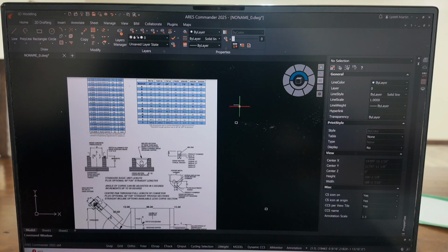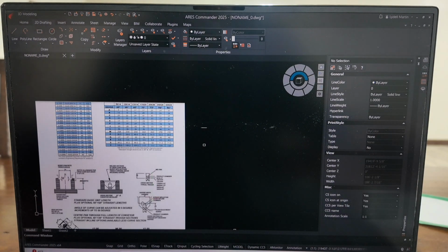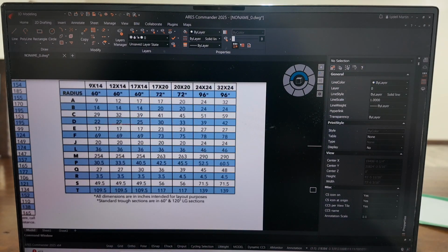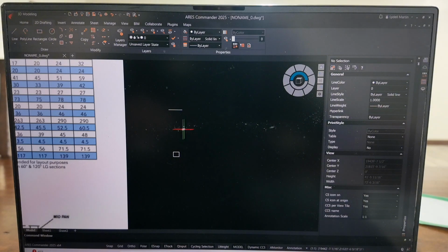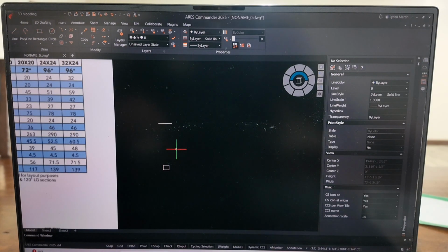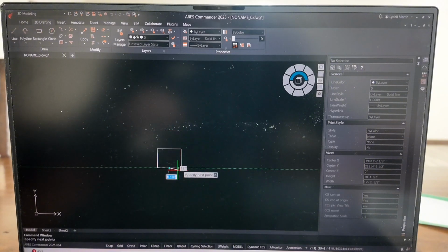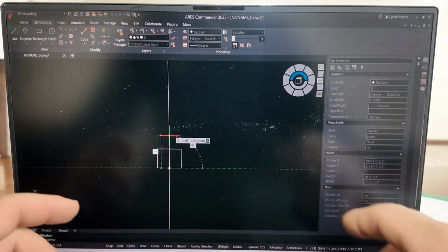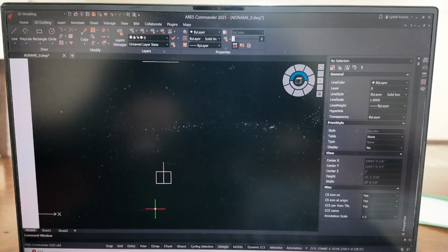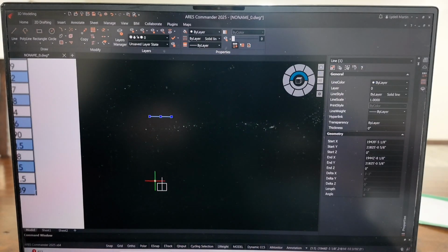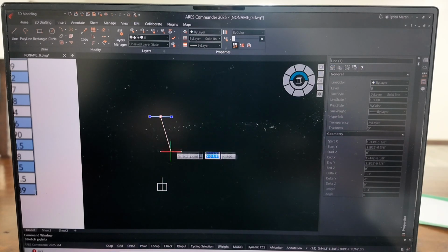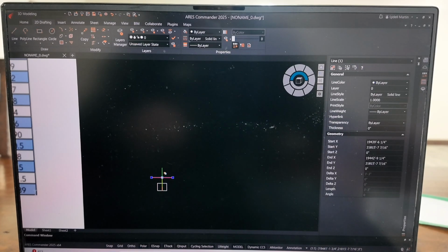Now we're going to hit escape. The height of that dump pit is D. The height of that dump pit is 25 inches from top to bottom. So we're going to take this here, go from the bottom of this, go up 25 inches, enter. That line is going to disappear. We just put that there as a measurement tool. After making that, I hit escape, then select this line up here, select the dot in the middle, move it down, and set it on top of that line.